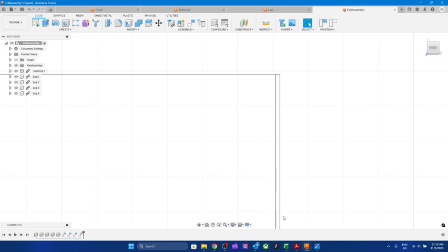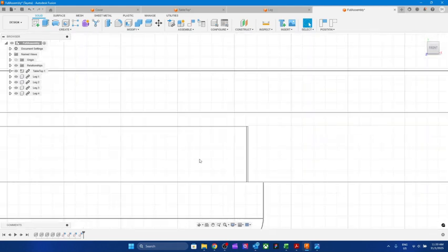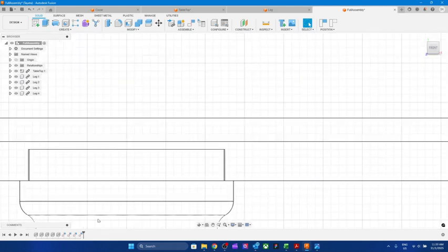So when the assembly people will be assembling it, all they will do is they will put either, and that's why I created the correct size. Why? So if it's a correct size, it will be snug fit, it will be tight fit, and it does not require alignment or anything. Because if you leave this sort of gap, for example, 0.5 gap, it can be that it goes loose, you see.